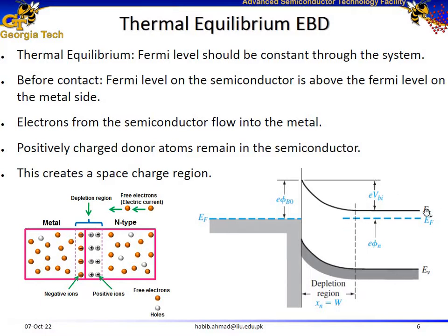Inside the semiconductor, this is lightly doped material, and over here we have metal, with plenty of carriers inside. So because this is lightly doped material, most of the depletion region or the band bending is going to be accommodated inside the semiconductor material. Here is your depletion width, which is going to be equal to Xn, or the width of the depletion region on the semiconductor side.